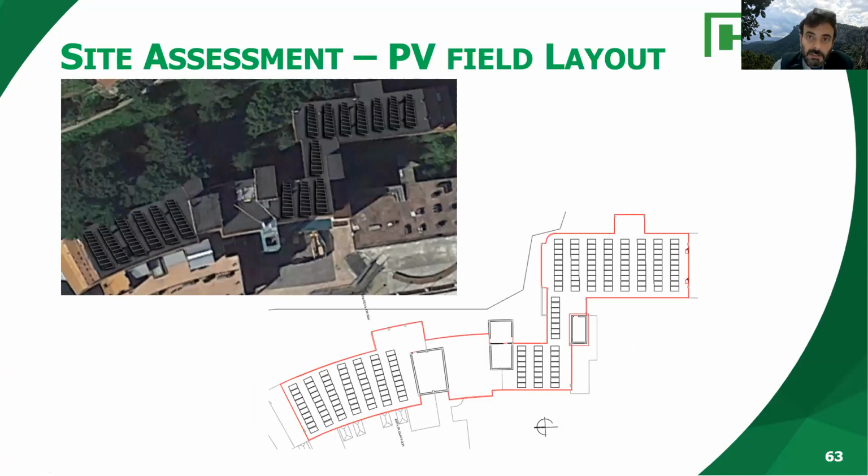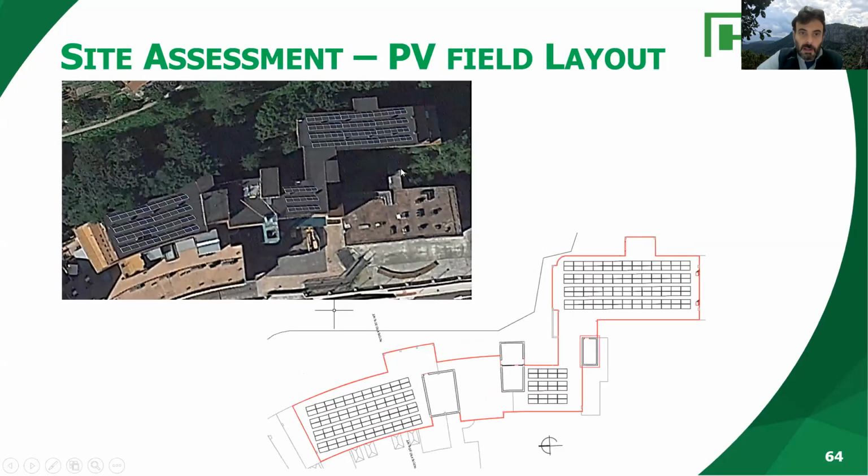Then this leads us to a very interesting case, which is that when we put the PV panels in these layouts, we need to space them considerably, as we have calculated. This is an example, but there is another way of putting the PV panels. Instead of putting them in rows like that, we can put them in this kind of fashion, like little roofs with different slopes.